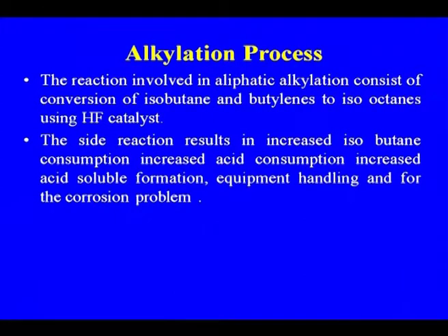The reaction involved in the alkylation consists of conversion of the isobutane and isobutenes to isooctane using HF catalyst or solid acid catalyst, whatever catalyst you are using. The side reactions which are taking place result in increased isobutane consumption, increased acid consumption, increased acid soluble hydrocarbons formation, equipment handling and corrosion problems.